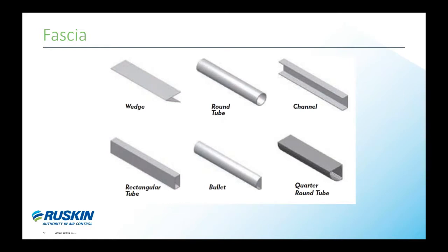The information shown in this slide is a list of the fascias and their profiles, similarly to the blades. Since fascias are typically made from extruded or formed aluminum, new profiles can also be made by pushing new extrusions to form the new profile. Since the fascia spans the entire width of the sunshade, consider design for the most efficient blade spans. For example, on a recent project, the customer in the Arctic asked for a totally new fascia to be produced to give a leading edge profile they wanted to see. It does not exist as a commercially available item, and we will create a new die for it.